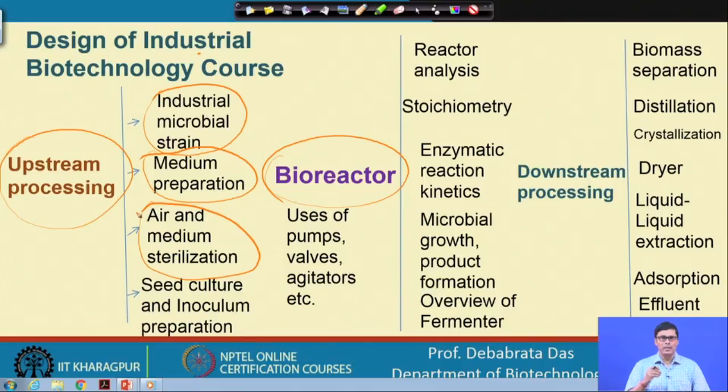I can give a typical example: I worked with a citric acid industry, and we produce citric acid by using Aspergillus niger from the cane molasses. As you know, yeast can grow very well in the cane molasses, and the doubling time of yeast is much less as compared to Aspergillus niger. So if even a little yeast enters the system, it spoils the whole fermentation process. They should be perfectly sterile. So air and medium sterilization plays a very important role.